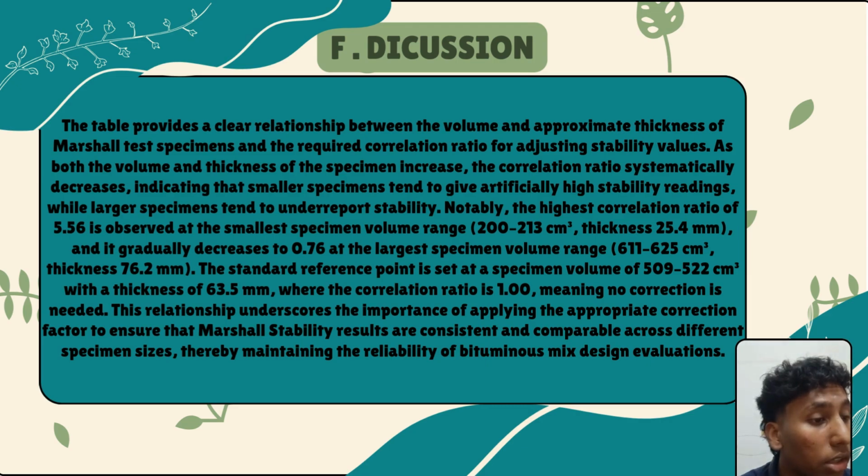Notably, the highest correlation ratio of 5.56 is observed at the smaller specimen volume range, which is 200 to 213 cm cubed. Thickness is 25.4 millimeters, and it gradually decreases to 0.76 at the largest specimen volume range, which is 611 to 625, and thickness 76.2 millimeters.